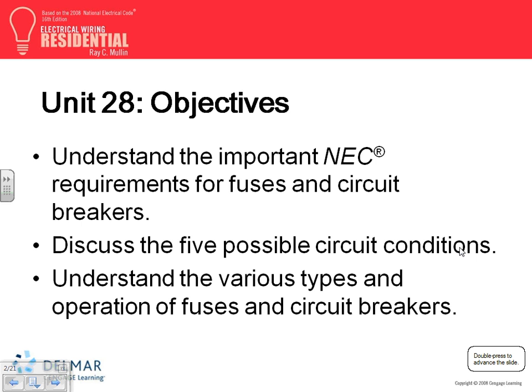Okay, overcurrent protection devices. We're going to talk, guys, about Article 240. Article 240 says if you have a piece of equipment or a circuit breaker, you need to protect the piece of equipment, the circuit breaker, from an overcurrent condition. The two ways of protecting are fuses and circuit breakers. Ground fault is later on. Every conductor, every panel, every piece of equipment, you need to protect from overcurrent condition. I want to emphasize, guys, the overcurrent condition.